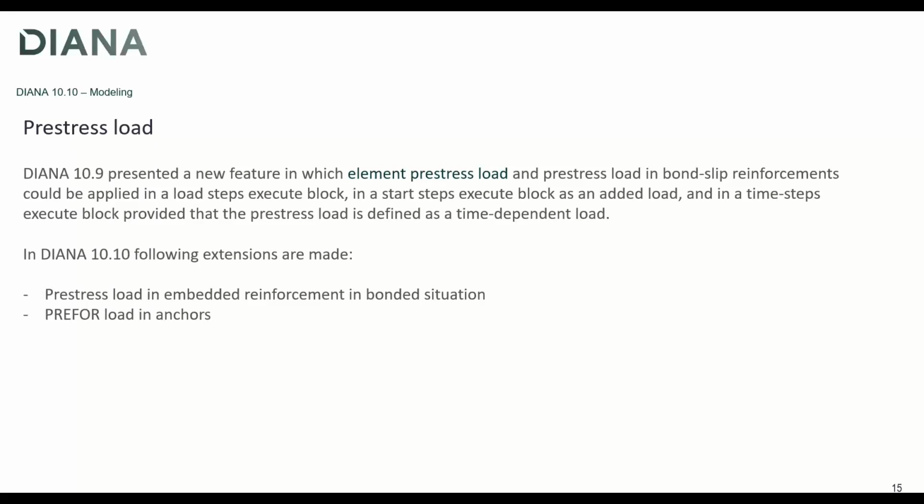Another new feature is, or let's say partly new because it was already available in 10.9, the pre-stress load. So in Diana, it was already available, and in 10.10, a couple of extensions have been made. So now it's possible to do that with reinforcement, embedded reinforcement in bonded situation, and also with anchor. So this is more an extension of an existing feature, to make it more complete.